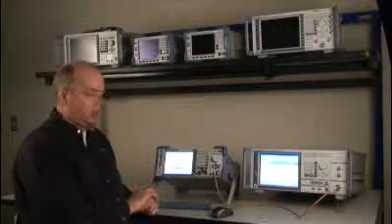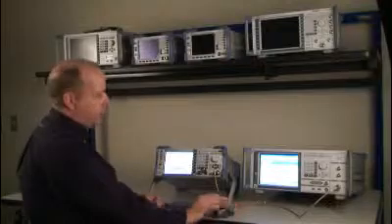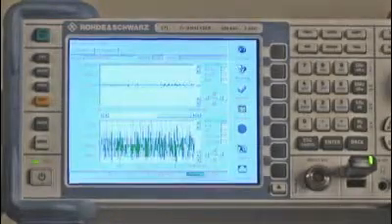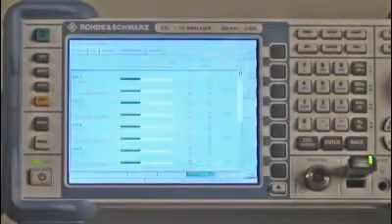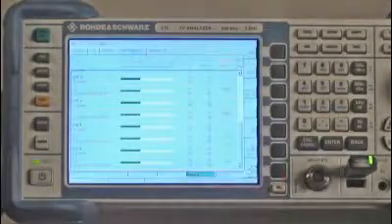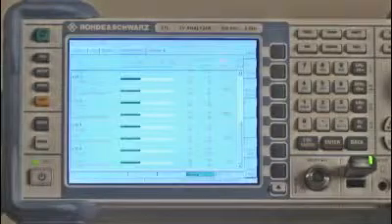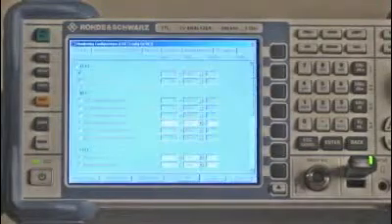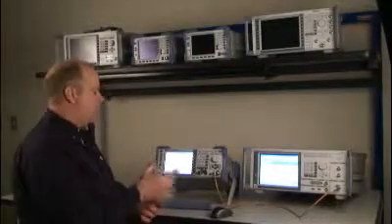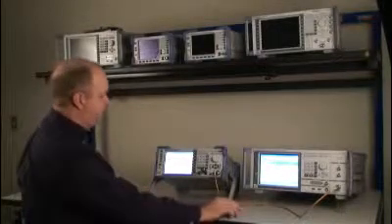Now, any of these measurements can be configured for your particular needs. And in doing so, I will go back on the right-hand side of the menu and pull up monitoring, and then monitoring configuration, either the soft key or a mouse click on the side, and then it'll come up with a specific monitoring configuration. And this is where I can go in and select any measurements, change any of the values, and also assign alarm lines.